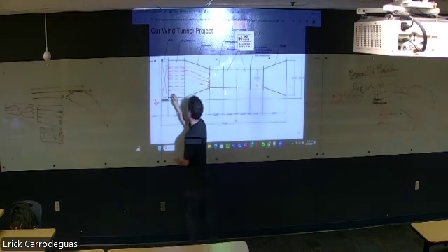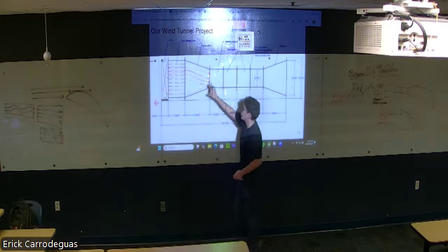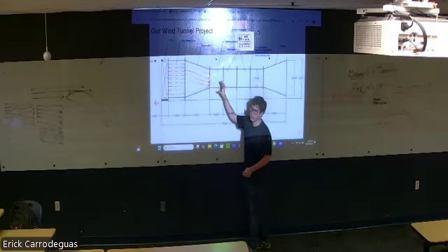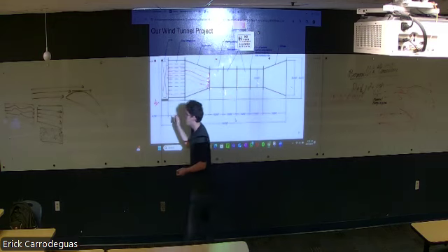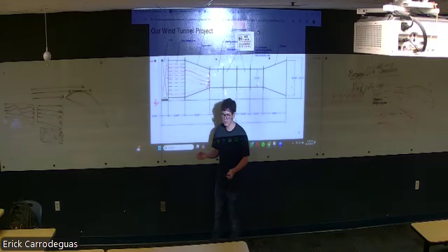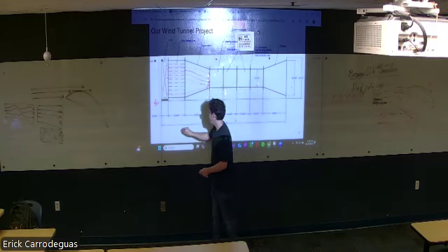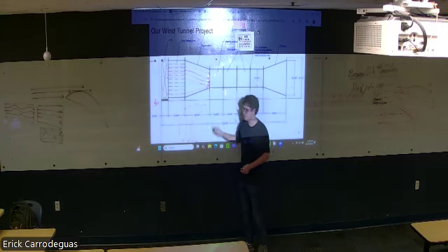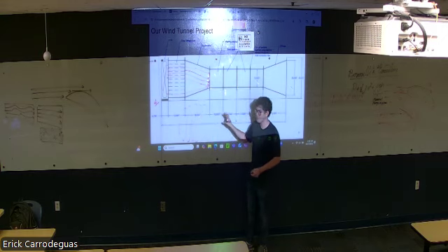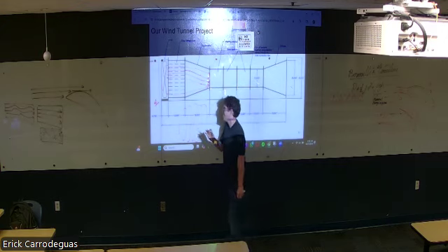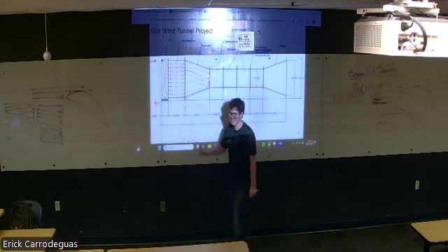It's no longer turbulent. So then we can control the flow of the air, and as it passes through the contraction, it stays as laminar flow. One difficulty that we have with a fan is that a fan produces what's called big eddies, right? Turbulent eddies. It's this big type of drag, a vortex. We can't have that in a wind tunnel. That would invalidate all our data, and we'd have to ignore all of that.